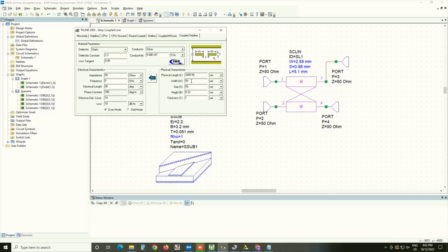And now we start setting, and the thickness is 2 mil. This is the strip thickness. Sorry? Oh, it's 3 gigahertz. Okay. Anyway, that should really not affect. It just changes the length of the transmission line one has to make. Okay. And now I can start specifying the width and the gap.